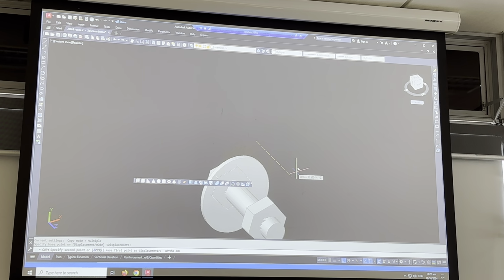Now you can do this by a comment, or you could put an arrow to one of them and put TYP. Does anyone know what that means? It's short for a tip for the teacher. No, it's not. TYP means typical. So if you point to one, it's typical for them all. You've covered that with one note. And you can do that with reinforcing too, and with other things in engineering. You can put the full word typical, but that generally is what we do in drawing.